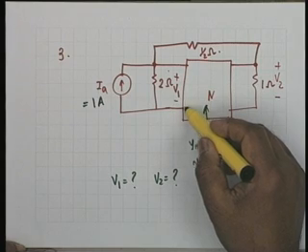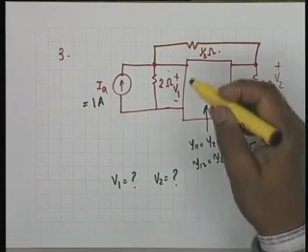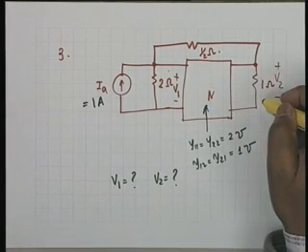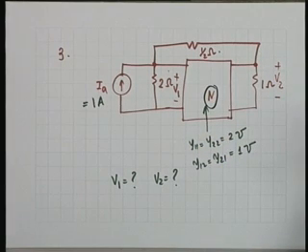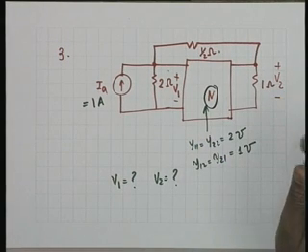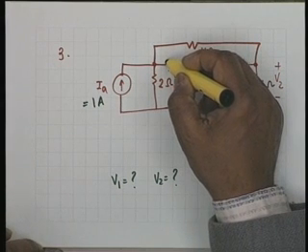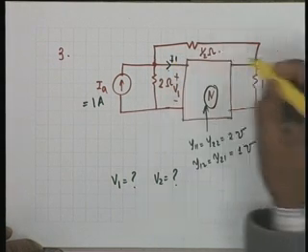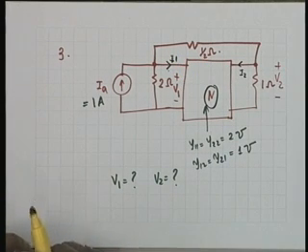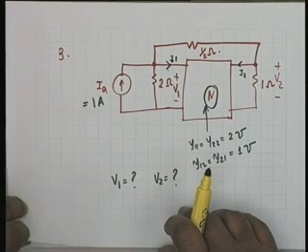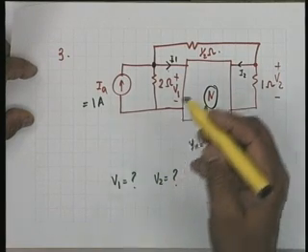Suppose you were told that this is a short circuit. Then there is absolutely no problem. You just find the y parameters of this pi network, add them to the y parameters of the network N, and determine I1 and I2. But this cannot be done here because it is not specific. Therefore, we postulate currents I1 and I2, and I write the KCL at this point.